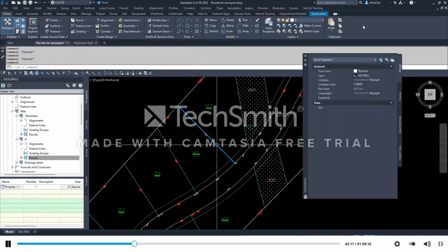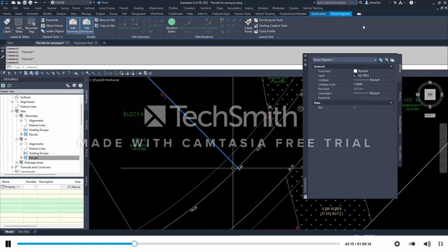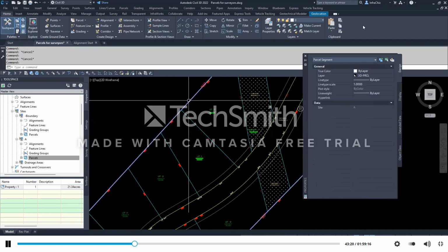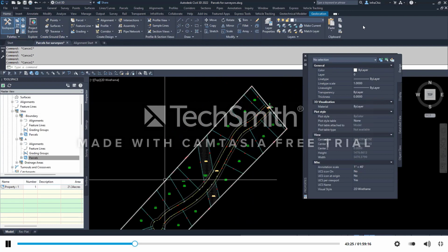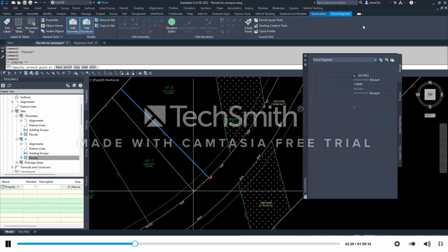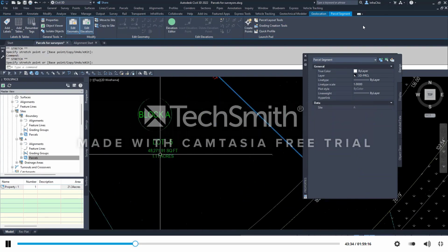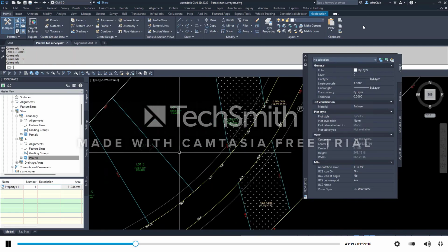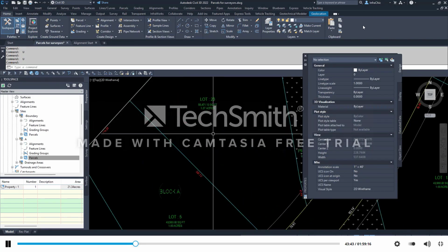All right. To know if your parcel line was a polyline or not, when you select one of these lines, if a diamond shows up at the bottom, it was made by the parcel creation toolbox. Whereas if I select this line, I get grips, square grips, that's a polyline. That's how you know. I can slide this with this diamond left, and look, that updated, and right, it updates dynamically. I can undo my slides so I get back to where I was. Right there, 1 acre, 1 acre.